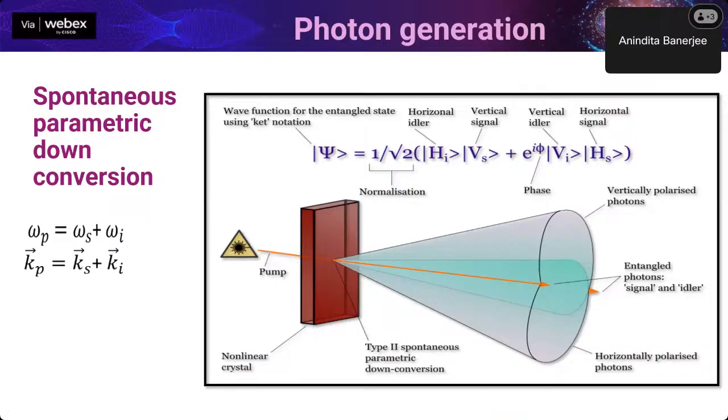components, including the optics and the lasers, the filters, lenses, all have to cater to the different wavelengths of light. And the most important is filtering. How do I filter the light? Because the pump gives me milliwatts, which is millions of photons, and out of the millions of photons, only 1 in a billion generates the daughter photons. So the task here is to separate the daughter photons from the mother photons of the pump beam, and as I already mentioned, the polarization is different. So we use those things to filter out.